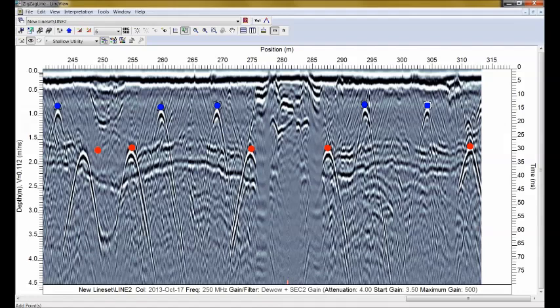Now, as I'm adding points, if I make a mistake, I can actually grab it immediately. If I accidentally click there, I can drag it over to a new location. The other thing I can do is, if I don't want this point, I can simply press the delete button and it will delete the last point I put in. My other option is to click on a point, right click, and delete it.